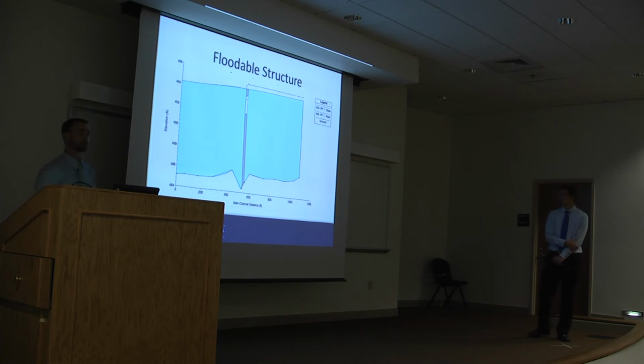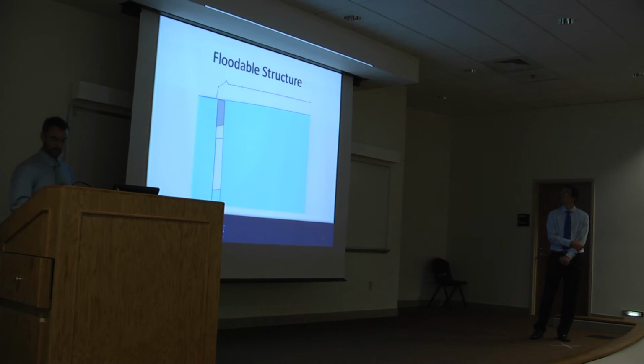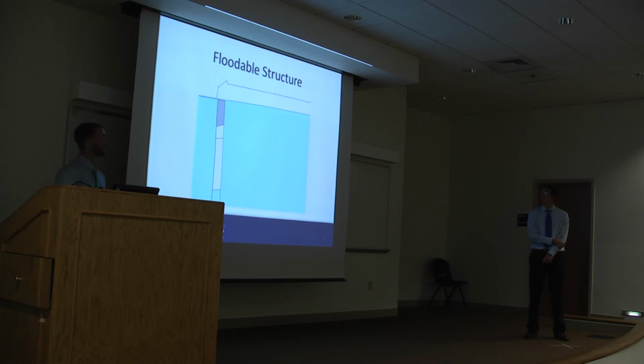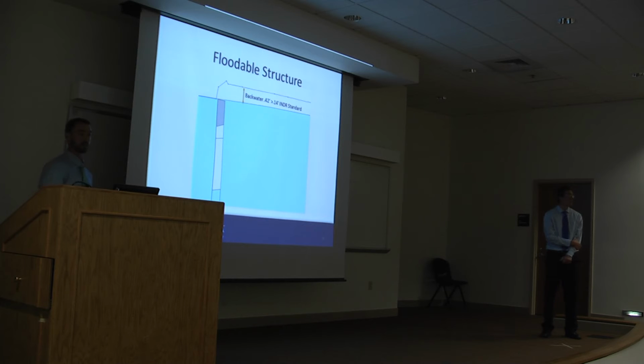So this is the water surface profile of our creek. This is the entire reach length of the creek, approximately 1,100 feet. If we zoom in here, you can see yet again the shaded in area is the original flow height of the creek before the structure was included, and the top line is after the structure was implemented into the creek, which had a backwater of 0.42 feet, which is significantly higher than the IDNR standard.